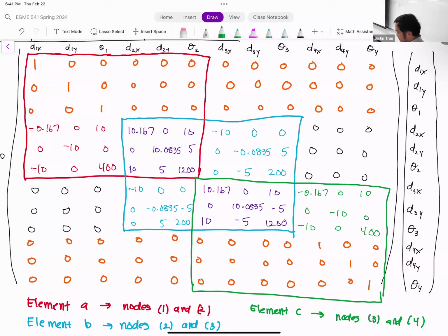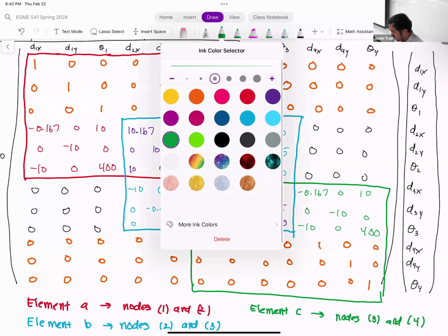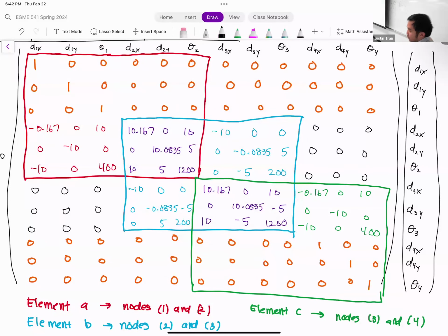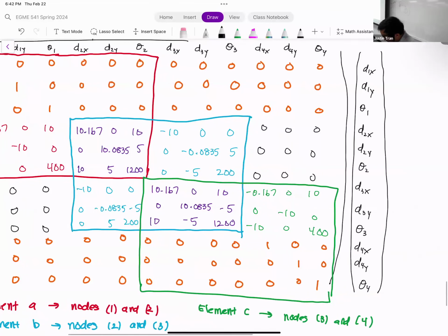Okay. All right, so the last part here is our forcing vector. Okay. So that's where our loads are going to be applied. Right, so thankfully this is pretty simple. So this is all equal to a 12 by 1 vector here. Okay. So remember, we have two loads here. We have a load that is applied on node 2 in the x direction. Okay. So for the first node here, we have 3 zeros just because that is a fixed boundary condition.